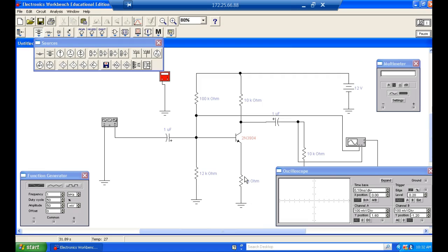Like they'll be soldering and leave the leads too long on the bottom side of the board, and when the board gets pressed down, two component leads touch together. Or they splatter solder across the trace and short things out. But I've never seen a resistor short. I've seen the resistance go up, and I've seen it open, right?